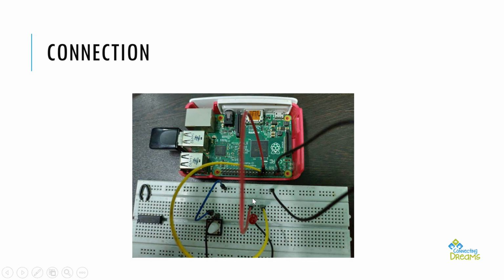Now, in case the user wants to forcefully turn off this particular appliance, the user can send a signal from the 16th number pin to the positive terminal as 0. So in that case, even though the switch is pressed, which is bringing the ground potential to the negative pin of the appliance, since the 16th number pin is not providing supply, the appliance will not turn on. So no matter whether your switch is pressed or not, by providing appropriate potential from the 16th number pin, it may be 1 or 0, you can turn off your appliance. So that is the basic working principle behind this experiment.